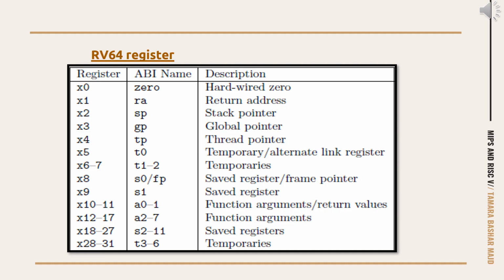In our presentation, we'll be focusing on the RV64 ISA. This ISA provides 32 64-bit general-purpose registers, spanning from 0 to 31. These 32 bits are referred to as a word. Register 0 is hardwired to 0 and cannot be overwritten. But each and every single one of the other registers has a unique name and a unique job description.